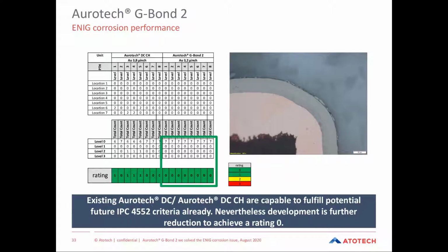What we typically do is that if we check one condition, we investigate a minimum of 6 to 8 PTHs per condition. And for these PTHs, we check different locations per PTH. So we typically investigate a minimum of 7 locations per PTH, which are the 4 corners of the PTH entrance and the PTH rings.